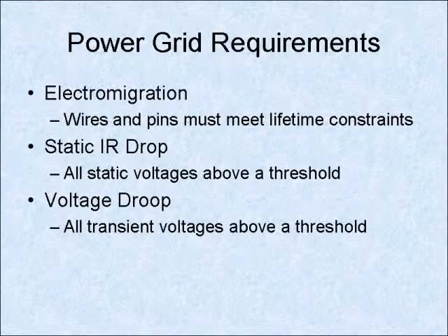Power supply network synthesis consists of generating a power grid to meet the various power requirements of a circuit. These requirements are electromigration, such that all the wires have a specific lifetime; the voltage drop at all the nodes in the circuit is within a specific threshold; and the voltage droop, the transient voltage drop, is also above a certain threshold.